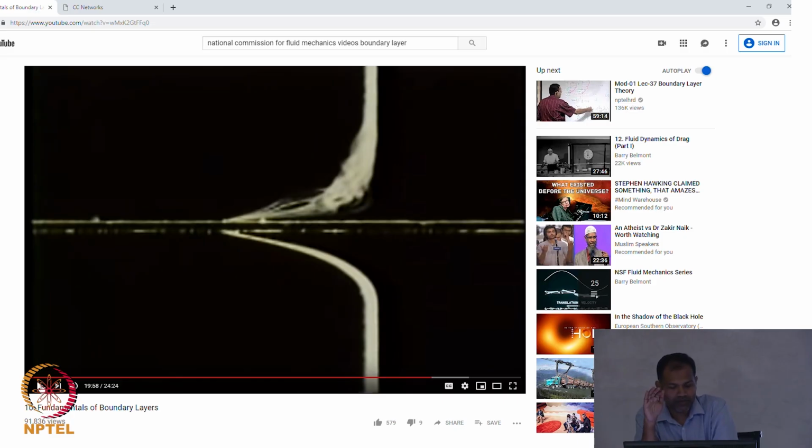Okay, so up is the turbulent boundary layer, bottom is the laminar boundary layer, and you can also see that in the turbulent boundary layer the profile is much flatter than in the laminar boundary layer. So, that is what we had even argued in the case of a pipe flow. Then they will draw a mean profile.